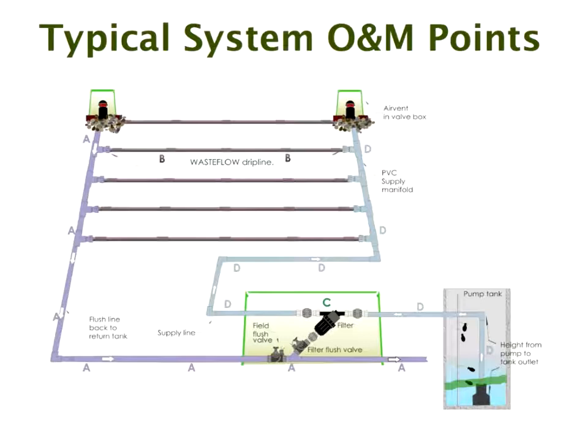Here in this particular drawing we've got floats, 4 floats. There are other systems with transducers of a different type, various types of transducers, or systems where you have sound or light bouncing off the top of the water to measure the depth and to send the signal as to when to go on and off. But floats, I think, still cover probably 90% of the systems in the marketplace.